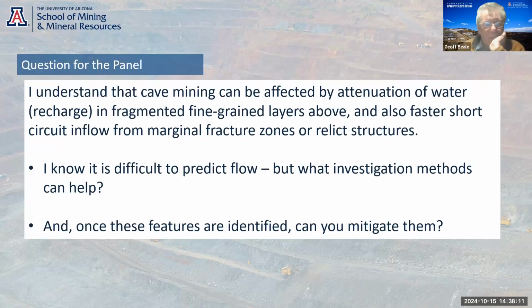No, I think predicting the pumping on a new cave zone is really difficult, to predict what the inflow rates are going to be, and therefore, if you're a deep operation, you can spend a lot of money in a hurry on large pumping systems. It's the same thing. You can back off on what you think you're going to need, and then you get a large rainfall event and you flood it out. So most people always go on the conservative side, but it is difficult.